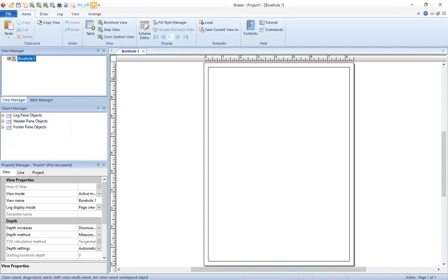For our first example, I'm again going to create a line symbol log cross-section that's based on LAS data. So the first thing I need to do is to open the location collars information into a new table. And then I also need to import the LAS data into a single depth table. We start out with the collars table because it's required to create a cross-section for any of these different data types or log types, because it's the only table that contains the well top, that is, the top XY coordinates and the elevation.